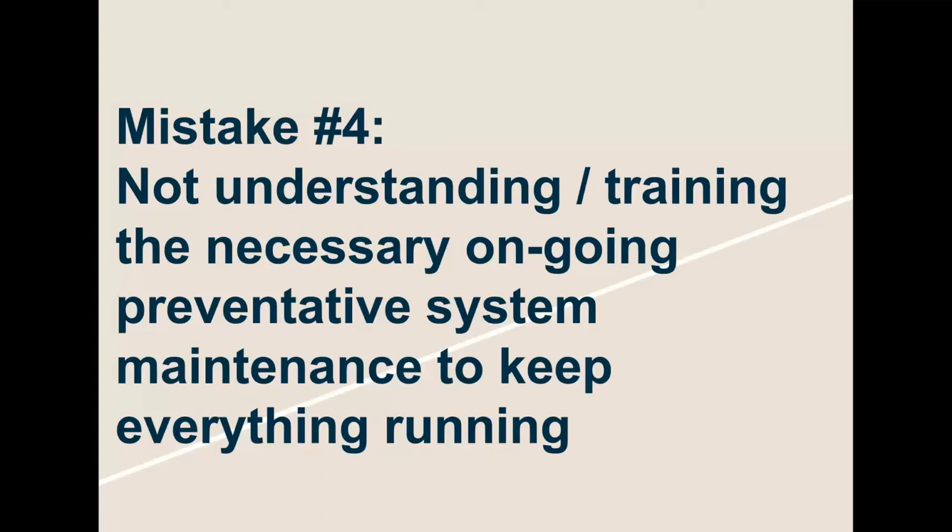Right. So the first thing is for everyone to understand that no matter what type of sensor you're using, the sensors need ongoing maintenance, whether it's in the form of bump testing the sensor or calibrating the sensor. No matter what type of sensor it is or how long it might last, there's always going to be ongoing maintenance in the form of calibration. The question is, how often do you do it, right? And that's probably the biggest question that we get.